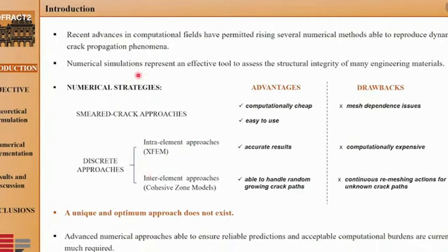Recent advances in computational field have permitted to write several numerical methods able to reproduce dynamic crack propagation phenomena. So these methods can be classified in smeared and discrete approach. The former represents the crack using a proper damage law, while the latter reproduces internal defects, including strain or displacement discontinuity, into standard finite element formulation. Each method presents advantage and disadvantage, thus denoting that a unique and optimum approach does not exist.